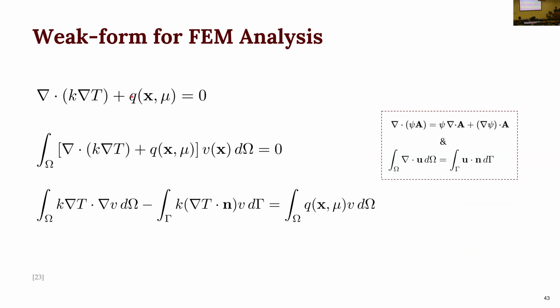So basically, we typically cannot find the actual solution, and we approximate with finite elements, and it's almost always less smooth. And this lower smoothness of the finite element approximations requires integrating the governing equation over the entire domain instead of solving them at individual points within the domain omega.